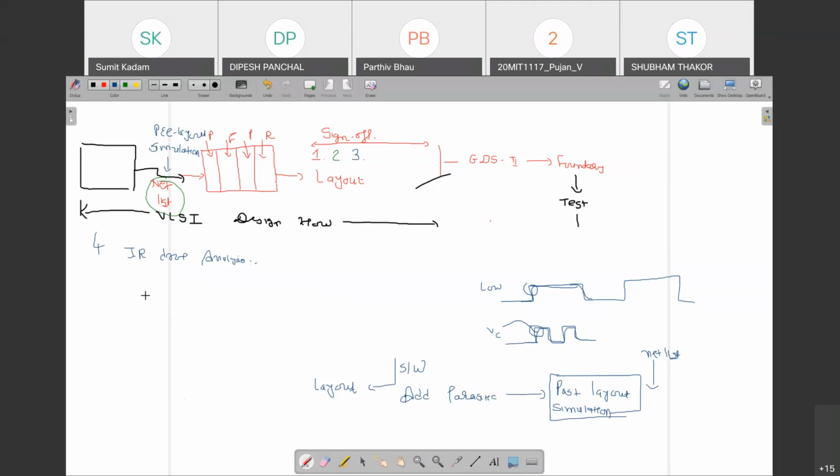So we have a wire resistance, and if we apply some voltage, definitely current starts to flow. In our VLSI, we call it a metal wire, so definitely it follows the resistance. If we apply the voltage, current starts to flow. If a very large value of current and R is available, there is a large voltage drop, which is unexpected.